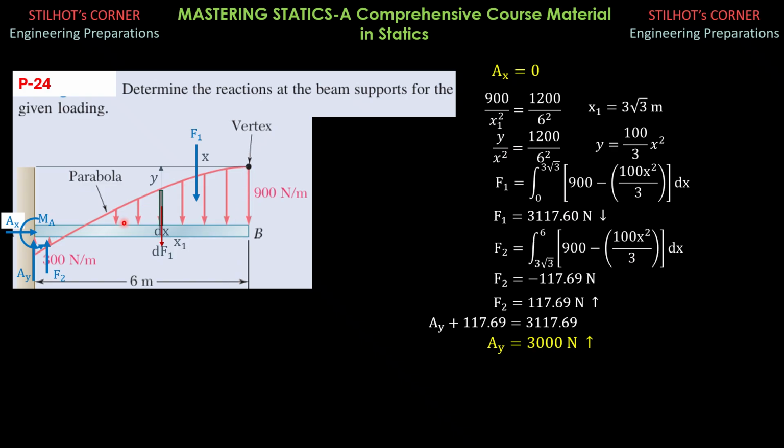Actually, I know that based on the derivation on distributed forces or centroids of areas, you can have that from integral calculus, but I already derived this, so I can memorize this. This is 3/8 of this parabola, 3/8 of x1. That's the expected value. For this case, it needs further analysis if we apply areas, but we'll just locate that by Varignon's theorem and using your calculator by integration for that part.